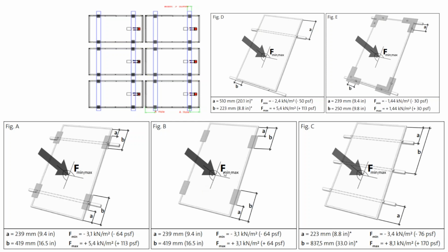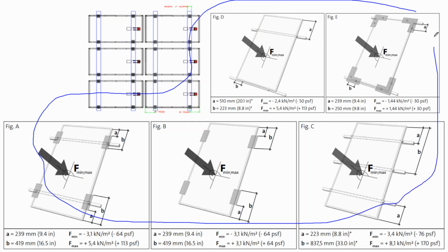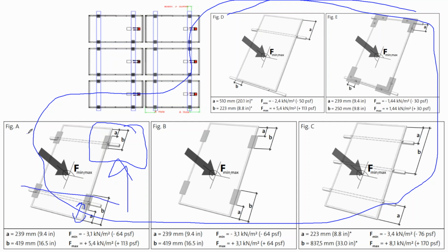So for example, here's a solar panel, and what it's saying is we're going to give you a variety of different ways that you can attach this solar panel to a rack. Installers will care deeply about this information called a clamping zone, which tells how far up the frame or close to the edge you can put the attachment points from the array to the rack, and that influences the deflection of wind load and snow load on the module. You will have to stay within those clamping zones in order to maintain your module warranty, but also you have to understand how these clamping zones impact the structure of the design.